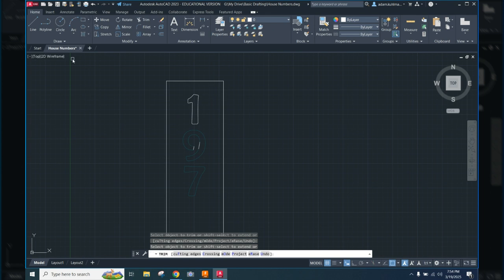All right, so what I want to do now is I'm going to go back to my selection tool. I'm just going to highlight the whole thing. I got to join it together one more time. And it tells me it joins 65 segments into one polyline. And if I highlight it, it all looks good. And so now I need to move and copy this number 9 here. So I'm going to highlight it, and I'm going to pick the copy button.